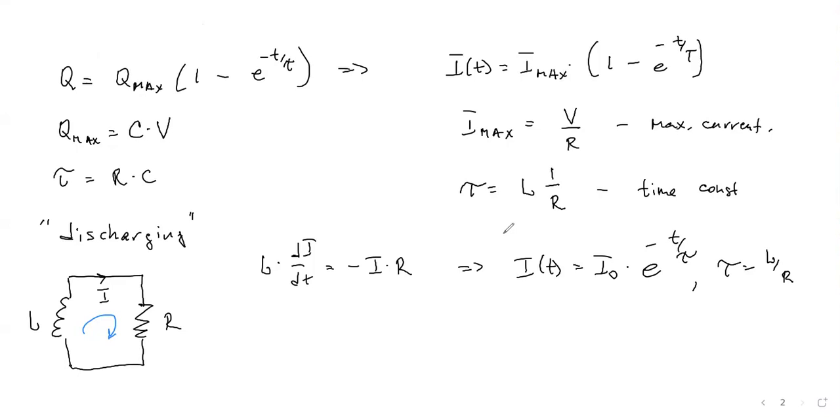So then if you remember for the charge, for discharging, we had the same equation, yeah? But I would rather want to show you some analogy with mechanics. This analogy with mechanics is always fascinating to me. If I try to translate this to mechanics, then I would say you have some inertia, the rate at which you change velocity. So current will play the role of a velocity, inductance is inertia, equals minus some coefficient,